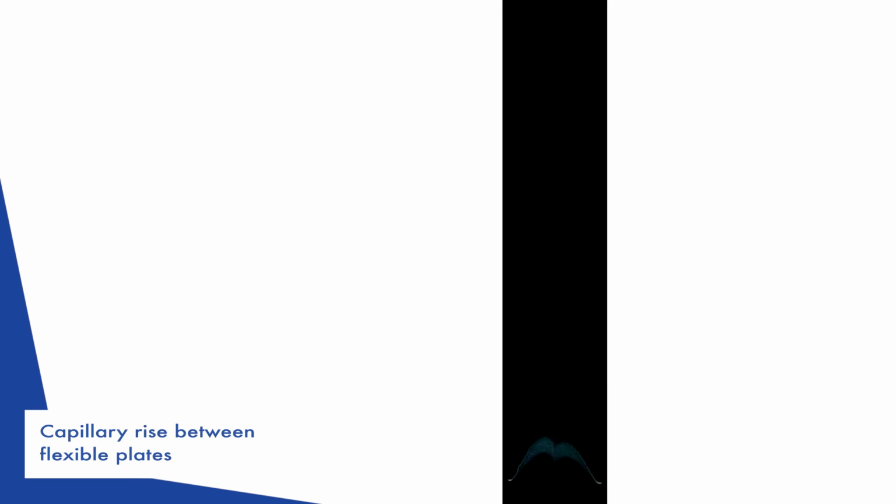Capillary imbibition is driven by the negative Laplace pressure due to the curvature of the liquid meniscus. Inside a deformable channel, the softness of the walls can be exploited to amplify imbibition. Here, a mineral oil rises between a glass plate at the rear and parallel to your screen and a thin, flexible plastic sheet whose left and right sides are kept at a millimetric distance from the glass.